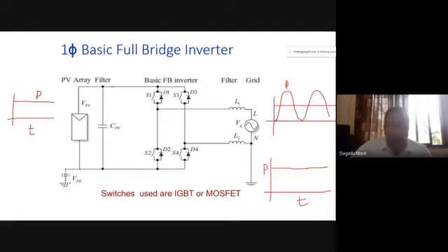So to balance this, on one side we are having a constant power. On the other side we are having the AC power. I am talking about the conventional inverter. Let us have a single phase conventional inverter. We are having a DC supply here. With this, our AC power is varying. It is not constant. And to balance that, on one side we are having constant power, on the other side we require a large capacitance. That will be a conventional single phase bridge inverter.